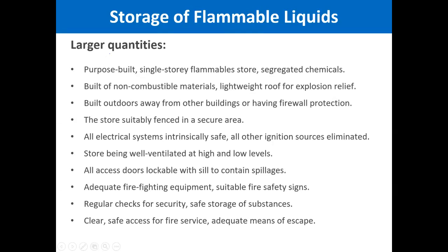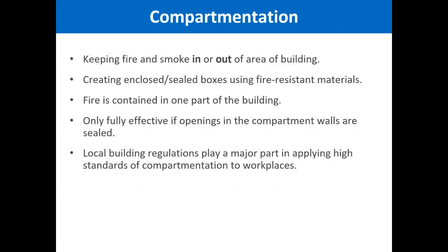Electrical systems should be intrinsically safe. So wherever you are storing flammable liquids, the electrical equipment in that area should be intrinsically safe. The store should be well ventilated, access doors should be lockable, fire extinguishers should be available, regular checks should be carried out, and clear, safe access should be provided to the fire services, fire brigade, etc.